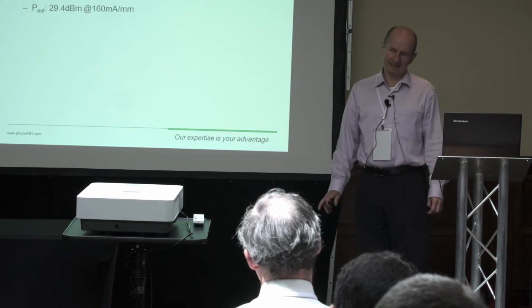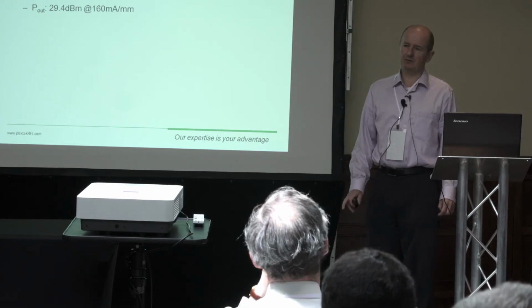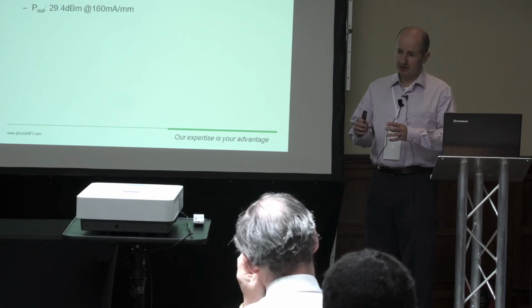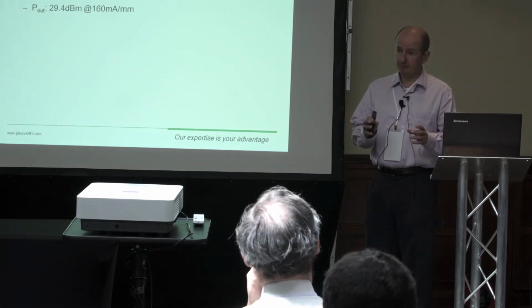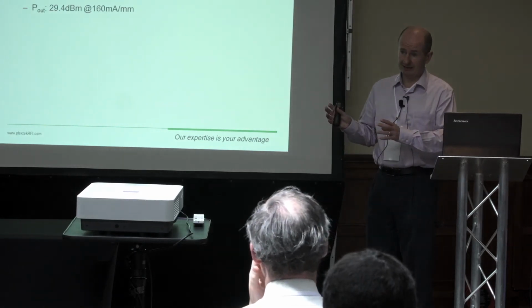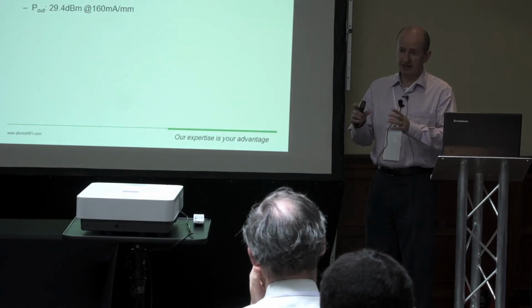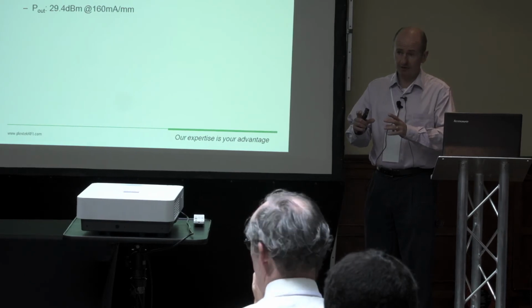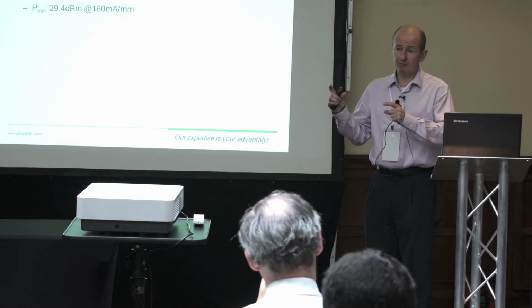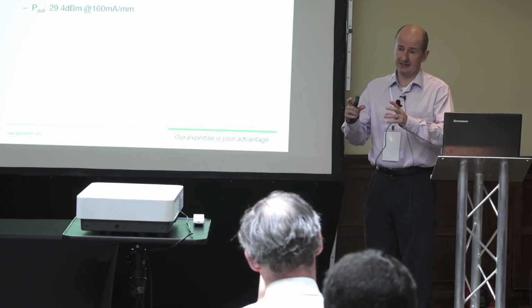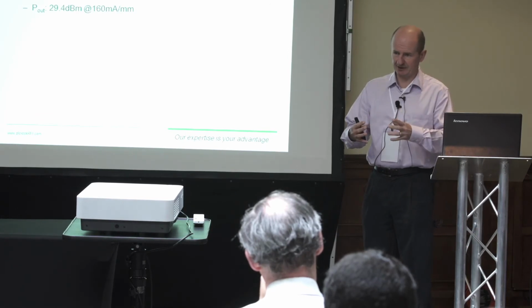No, I'm not quite saying that. I mean, gallium nitride can be a little bit more efficient, but the key thing I'm saying here is that for a much lower die area, you can get an improvement in IP3 using GaN compared to GaAs. That's really the message I'm trying to get over.